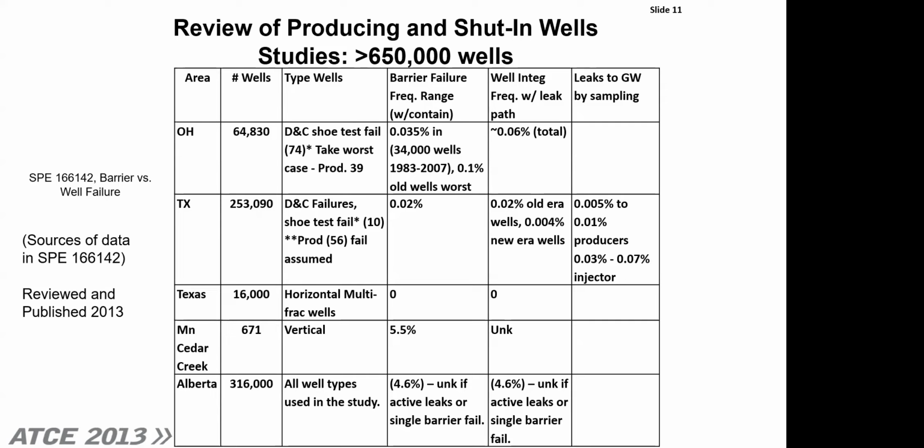So that is an issue. Notice that most of the older wells have a much higher leak rate than the newer era wells. A lot better technology being used, a lot more knowledge about what is going to work and what won't work. And so that is an element that we really need to look at. But what it says here is you need a lot of information. You need good background on everything that is going in here. But look back at some of these old things, and you can see that when you didn't have a lot of barriers, your cement wasn't good, you're going to have a lot of orphan wells that leak, or shut in wells leak, or even plugged and abandoned wells that develop a leak later. Next slide, please.